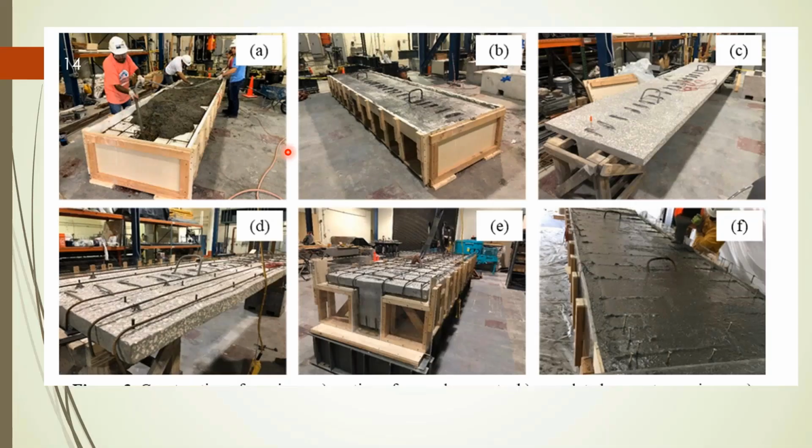So we said, let's do the study, but more than anything else, since we are going to be placing this very thin layer of the UHPC around the concrete, I want to see how it flows. So we took a T-beam, we sandblasted it, and we built epoxy glass formworks.